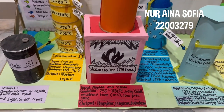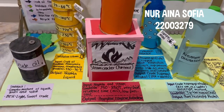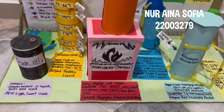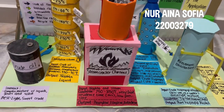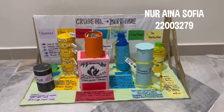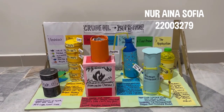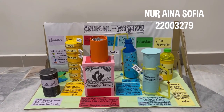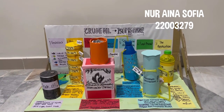After quenching, compression, acid gas removal, and drying, it enters a demethanizer to remove methane and hydrogen. A deethanizer separates C2 compounds while heavier C3 to C5 streams go to a depropanizer. The C3 fraction is purified in a C3 splitter with 120 to 200 trays to produce at least 99.5% polymer grade propylene. Finally, the C4 stream undergoes extractive distillation with NMP solvent to recover 99.7% pure butadiene, while the C5 fraction is processed to obtain aromatics such as benzene, toluene, and xylene.